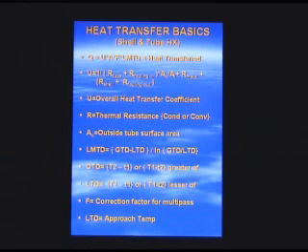Here we take an area ratio to basically convert all of the heat transfer coefficients to the outside tube surface area. This is tube metal resistance based on the type of tube that we elect. Stainless steels have a higher resistance than the carbon steels do, so there's a slight penalty for the alloys. Then we have the shell coefficient and a shell side fouling factor. Evaluation of this equation gives us an overall coefficient.